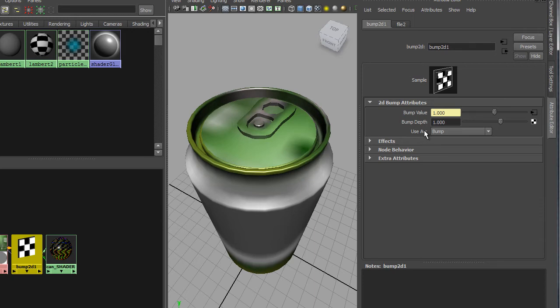For those of you that did the optional video where we created a normal map, for those of you that had a PC at home and wanted to install that Photoshop plugin, you can actually use the normal map that we created from that. And in order to do that, you have to set use as to tangent space normals. Okay, if you're just using the bump map version, the black and white one, just leave it on bump map.